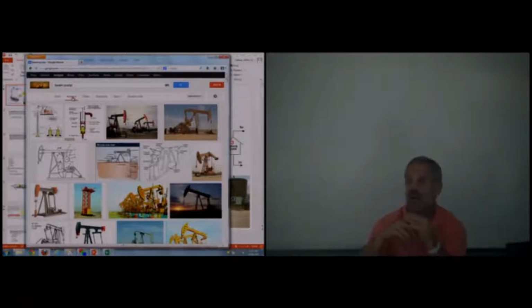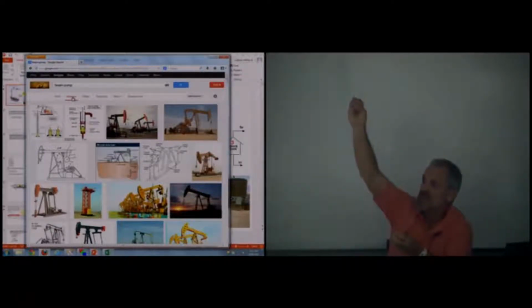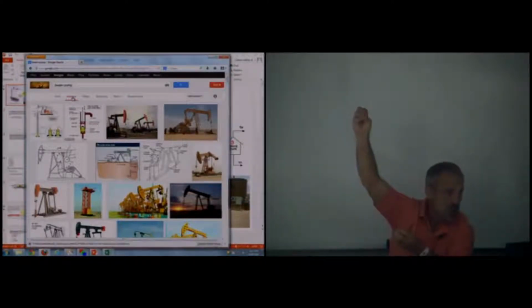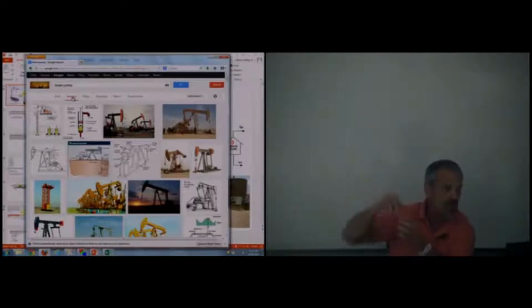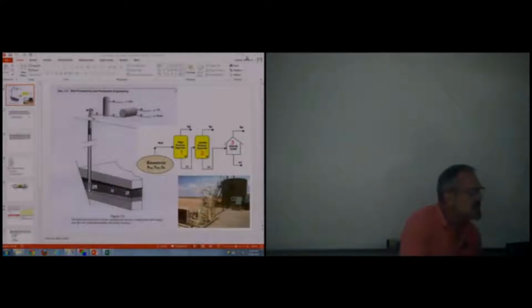Okay, so with the same bottom hole pressure translated to the surface, I lose less surface pressure if it's a gas column than if it's an oil column, than if it's a water column. So gas usually flows to the surface, even if it's lifting a little bit of water or condensate with it. And so typically, but not always, we would